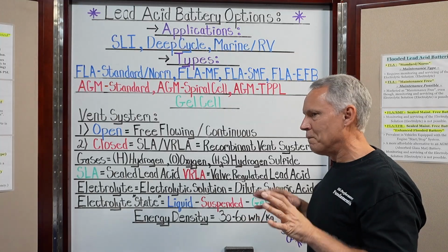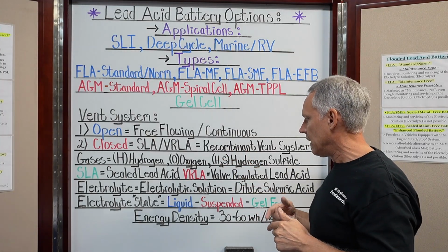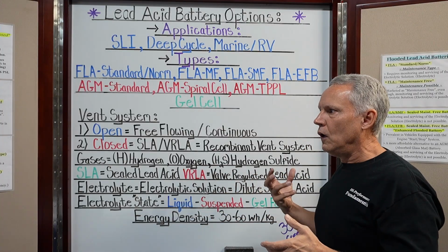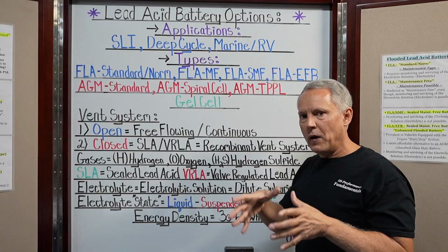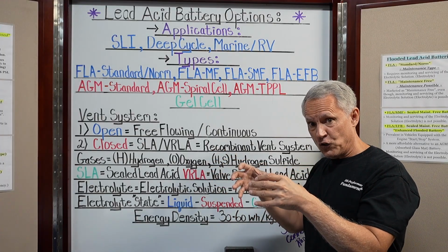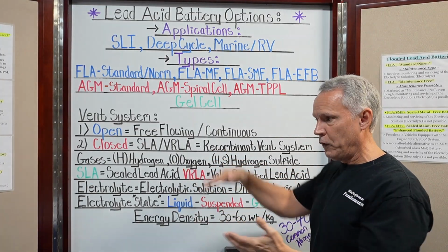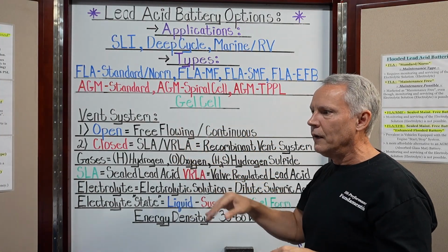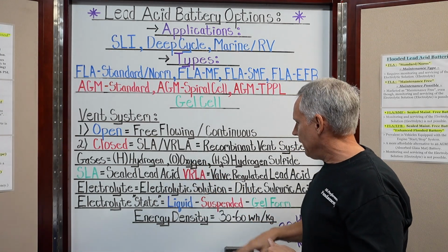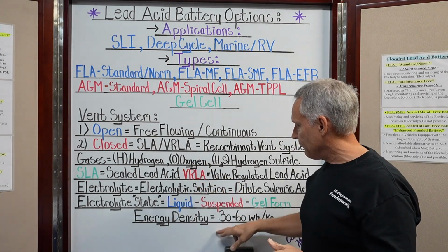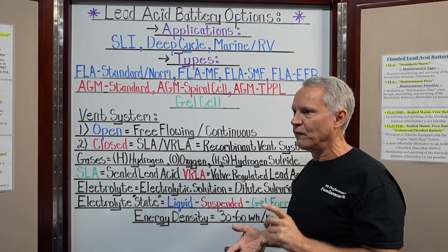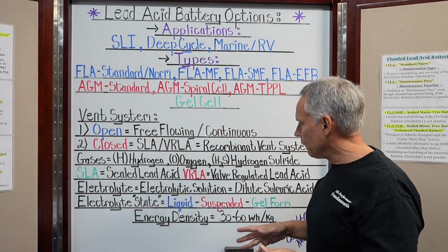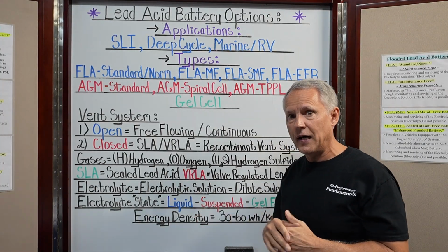And that's why one of the big benefits of a lithium-based battery is that it has great energy density and it's much lighter. So for the guys out there who not only want that energy density, but also want it to be lightweight or a smaller package, maybe it's packaging, because if it has a much greater energy density, we can make a much smaller battery, so it's physically smaller and can fit into tighter places or cramped spaces. The bigger battery is physically bigger to have the same energy, it's going to be bigger and weigh more. So for performance applications, you don't want the weight, and for certain applications, you don't want the size. So there's a lot of benefits to lithium batteries. There's some definite downsides, we'll get into that also.